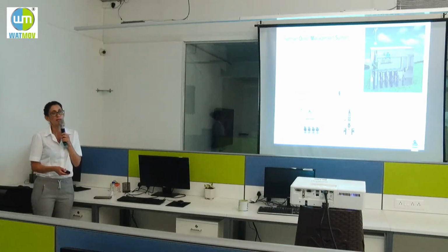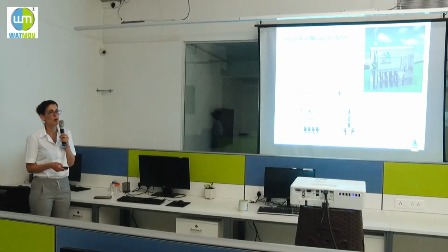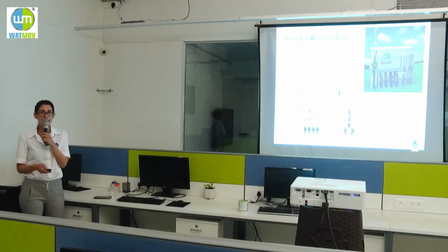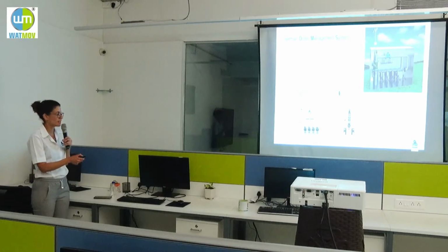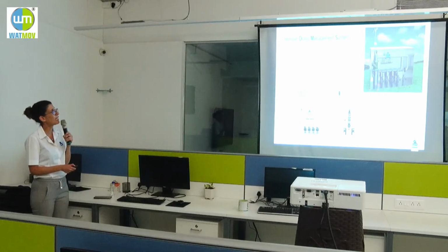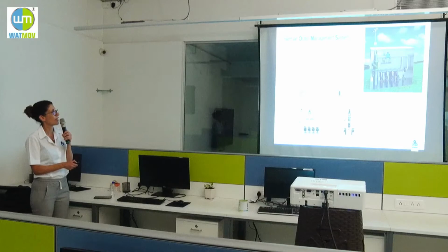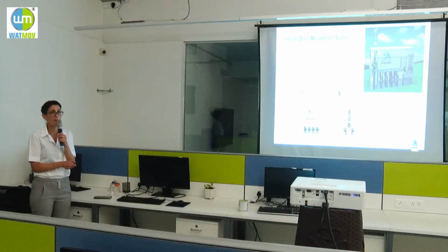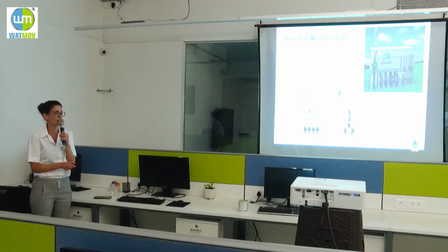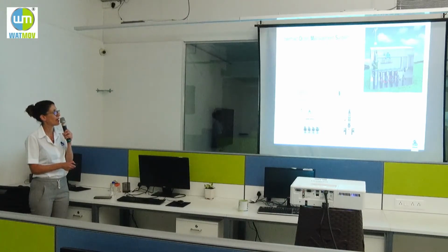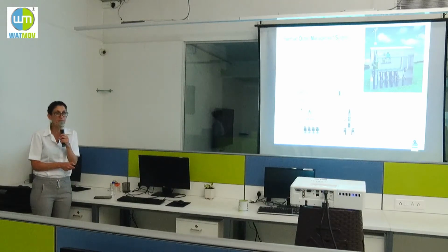And at the beginning, of course, we were making drawings and 3D drawings for each OMS, okay? So you can see the OMS, this is the inlet to the OMS from the distribution line. This is the strainer, a stone trap, as we said, and a combination air valve for air management. Water meter for 30 hectares, okay? And then we have what I call the plot valves, flow and pressure control.